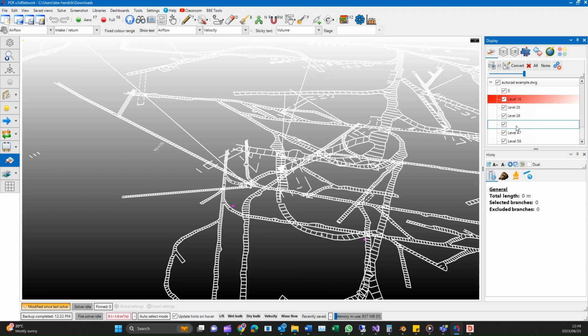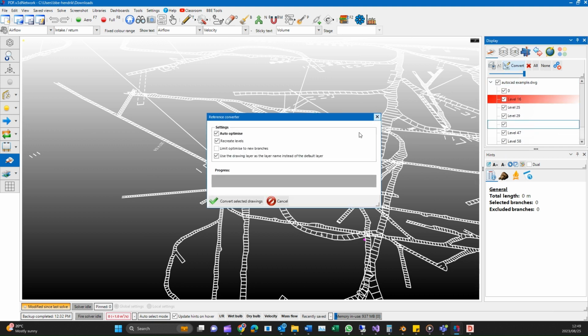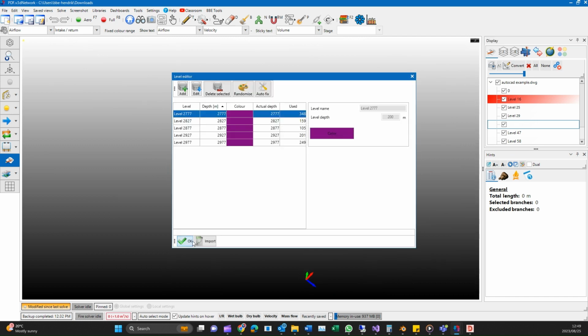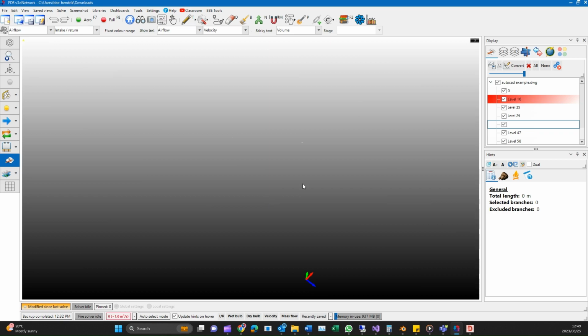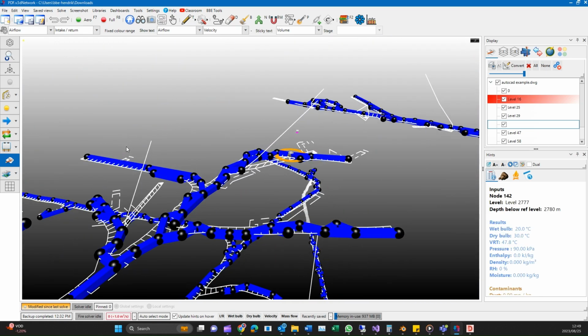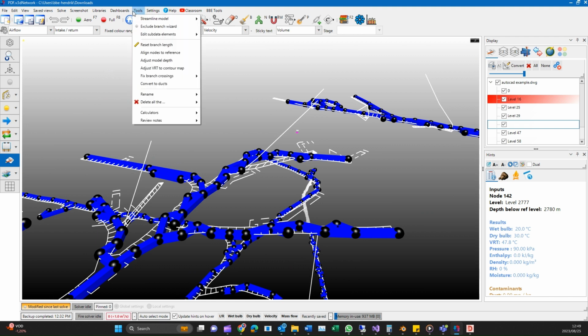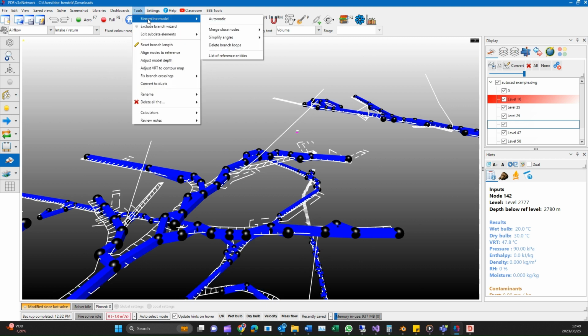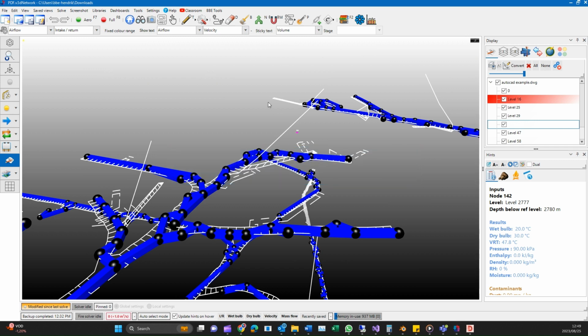To do this, select the required drawing or required reference layers and click on the Convert button. Set your preferences on the next screen and click on OK to continue. Depending on the source drawing, especially if it was not centerlines, you might have to do some further cleanup post-conversion. To speed up the process, look at the Streamline Model options under the Tools section.